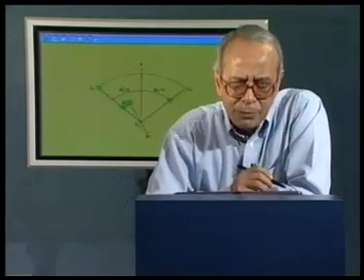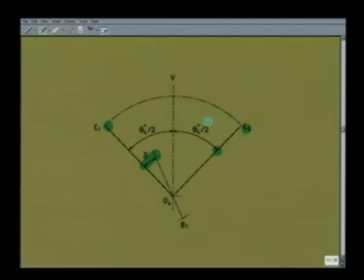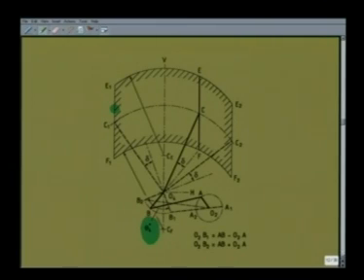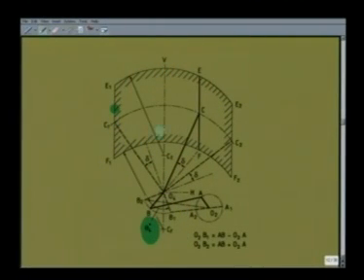Now, the third part of the problem, we can have some more specifications. For example, we define the width of this wiping field, that is this horizontal distance C1, C2. So let me pose a problem that modifies this design, but you are allowed to change only the crank length O2A, the coupler length AB and the angle delta to satisfy three requirements, namely the wiping field should be symmetrical about the vertical line O4B, the width of the wiping field, that is the horizontal distance between these two extreme positions E1F1 and E2F2, is say 450 millimeter to the same scale, and there should be no quick return.